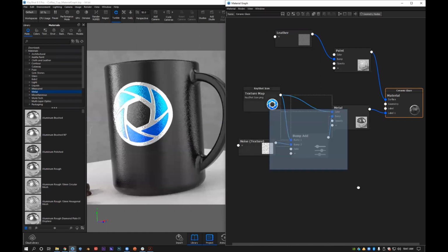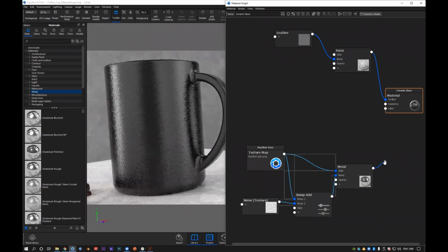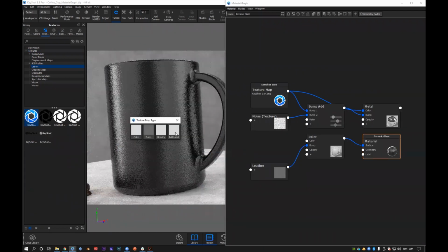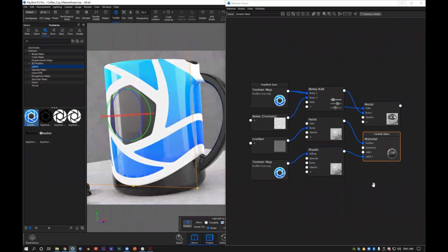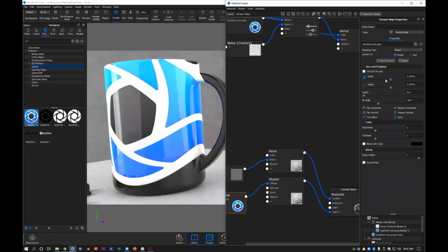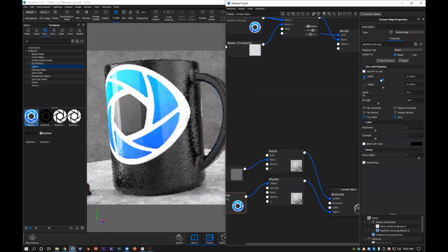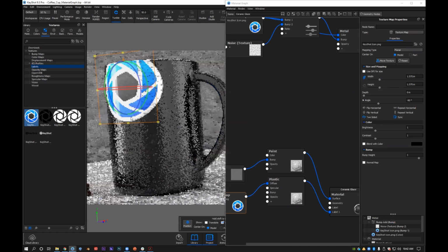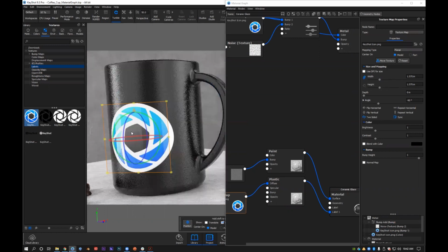So I'm going to disconnect these, and let's run through making a label real quick. In that case, I use the KeyShot logo, and I'm just going to drag and drop that onto there. I'll select Add Label, and then let me clean this up real quick. So here's my label that I just added, and I want to scale that label down. I can do it outside of this, but since this is open, I'm just going to do it right here. So I'm going to scale this label down into something that's usable, and then I'm going to move that label so it's more centered.